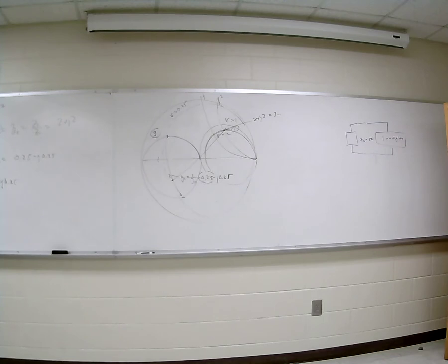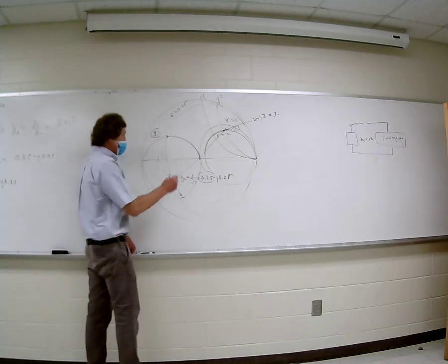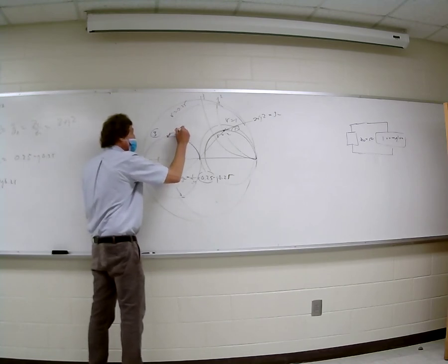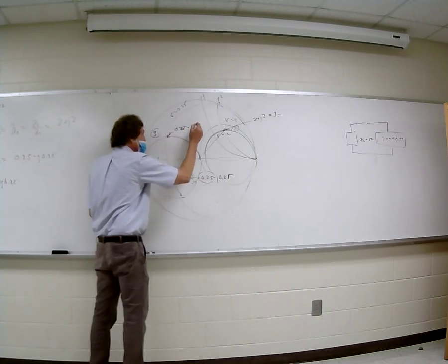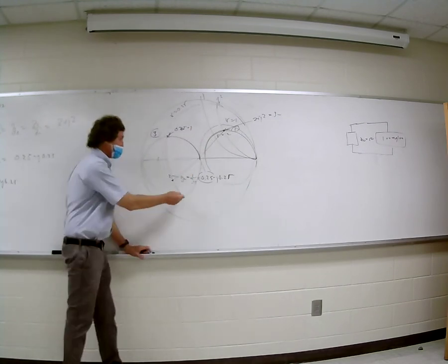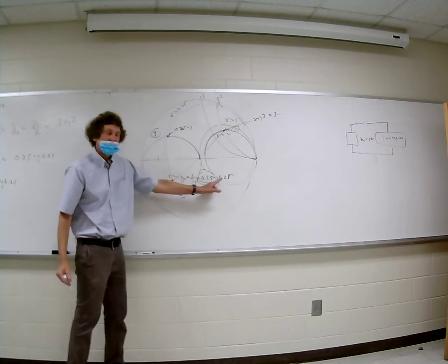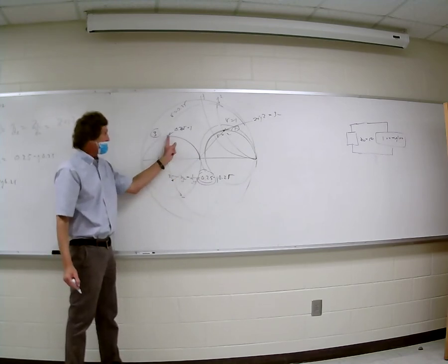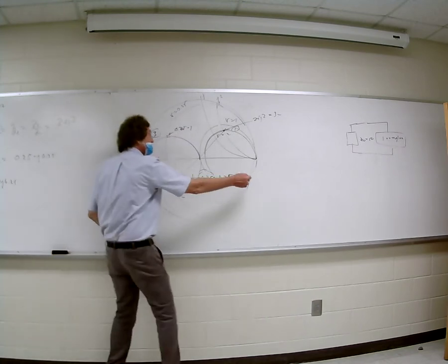That would be out here. It's going to be like 0.425? Plus 0.425. Wouldn't it be 1 because you're on the 1 circle? No, you're on the rotated 0.25 point. Remember, we're at 0.25. That's the trajectory. We can add or increase the imaginary component, which means you're moving up and down here, right? This is not the 1 circle, it's the 0.25 circle, isn't it? Y'all with me on this, class? The 0.25 circle is this big one.